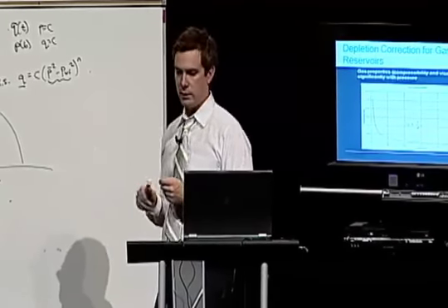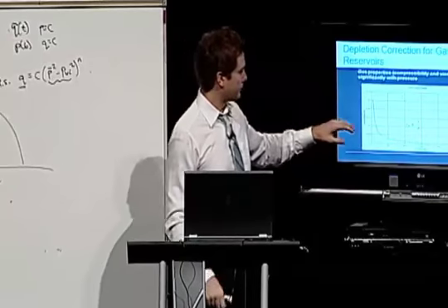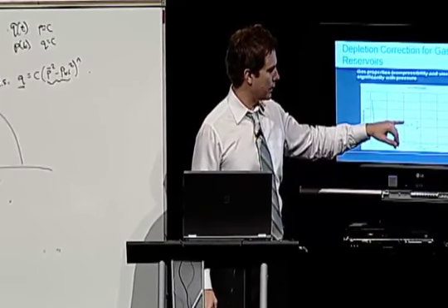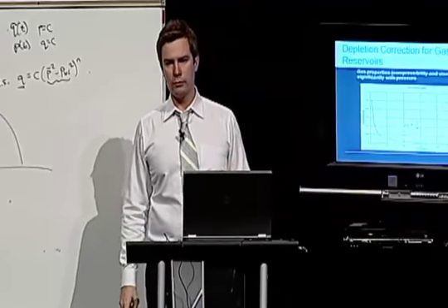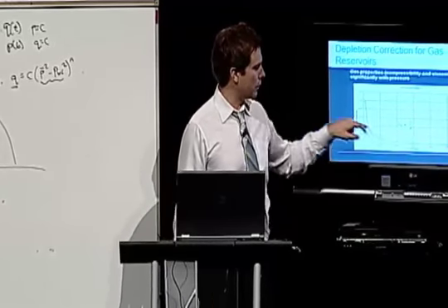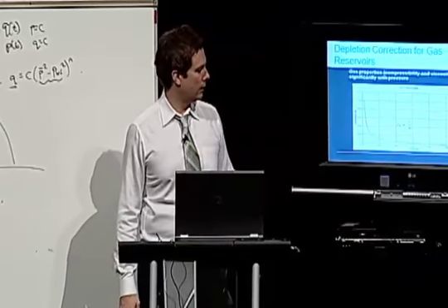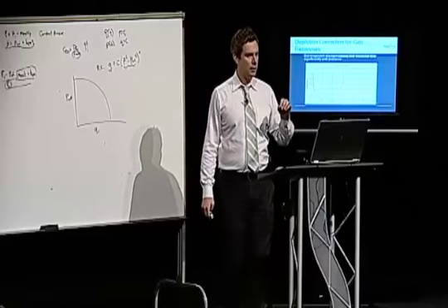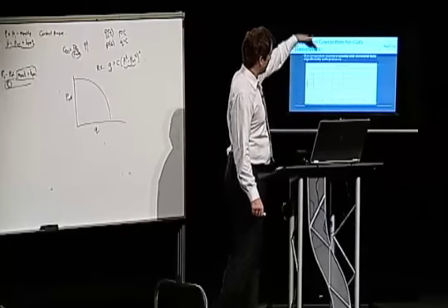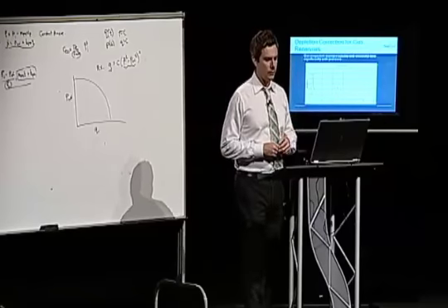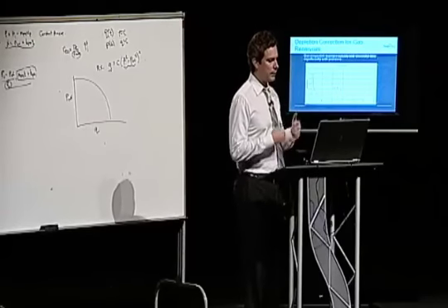And pseudo pressure is not going to be enough on its own. So again, I drew this on the board earlier. Gas compressibility is roughly equal to the inverse of pressure. And so when we plot it, it's going to have this very strong nonlinear shape to it. At very high pressures, gas compressibility is reasonably well behaved. But when we get into low pressures, it expands and sort of goes through the roof and increases quite dramatically. So we need a way of handling that.